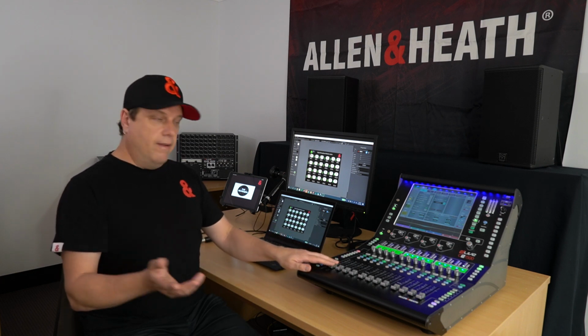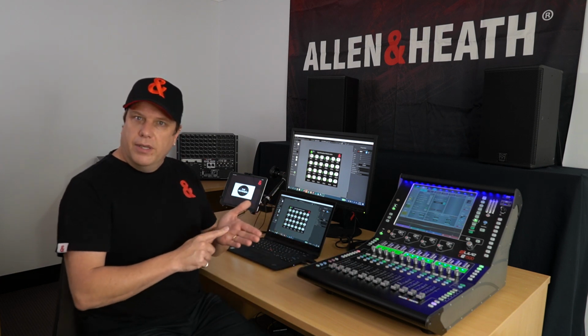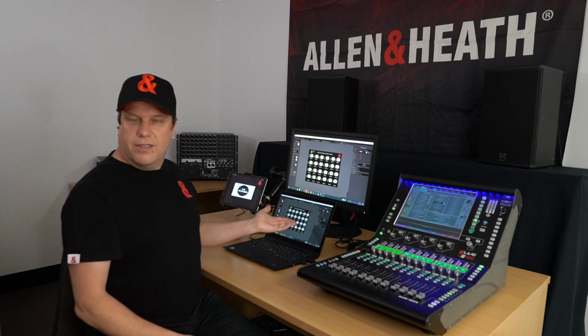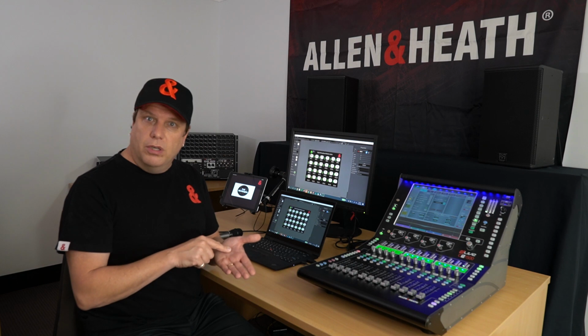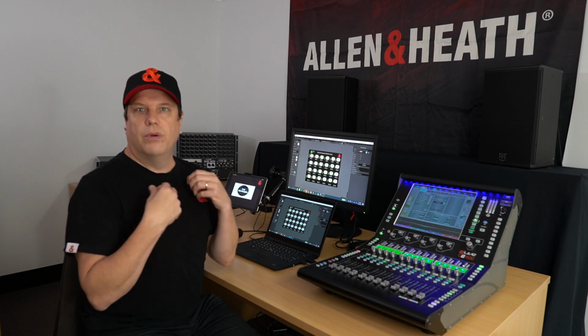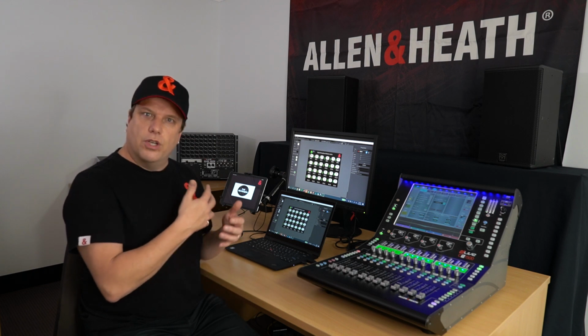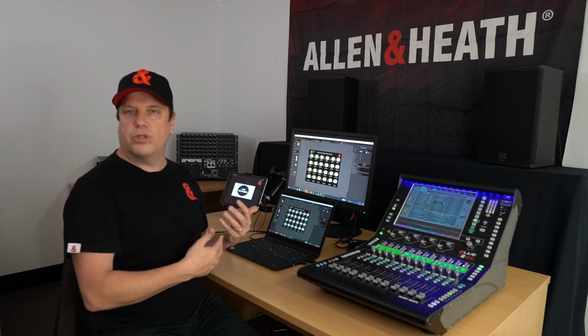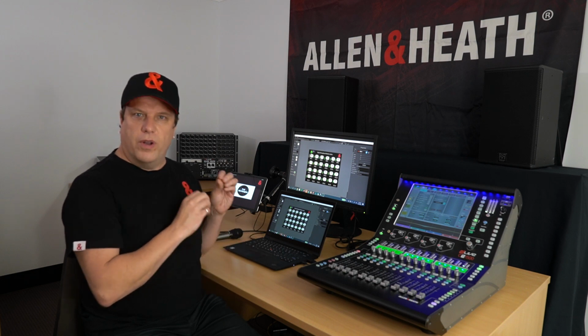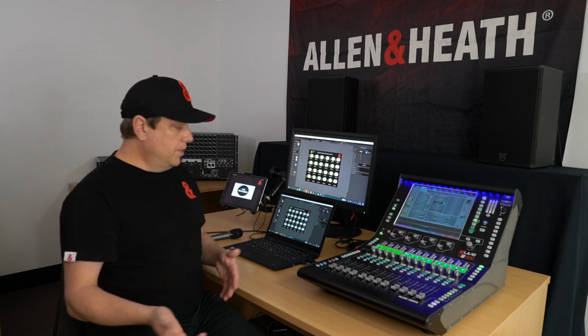They can hear it. They can then jump to their iPad app and normally they can see it. They can see the metering of what radio mic's freaking out. But if in doubt, they can sit there and solo it to find the mic that's broken. And by the time the cast member is coming off stage, they're standing there with a new lapel or headset or hairline mic to replace it, and we're moving on with the show. I don't have to jump on comms and tell them that something's broken. I've given them the resource to know that it's broken, and I've given them the resource to help them solo and find out and fix the microphone.